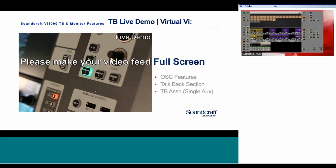When it comes to stereo buses, in this case AUXes, excuse me, when you click it the first time, it sends to left and right. When you click it a second time, it only goes to left and then to right. When it's a mono aux like aux 9, it's only on and off. And then when you want to deselect all of them, you can just push none.